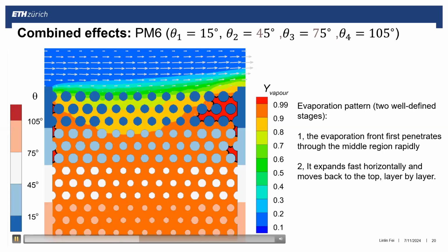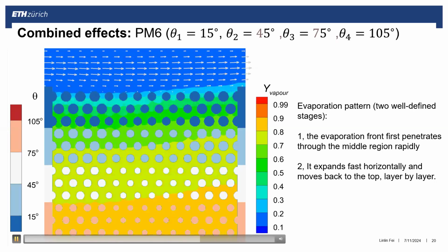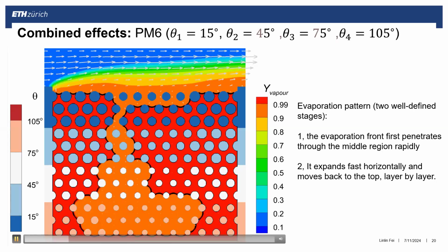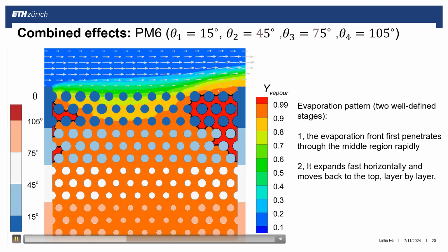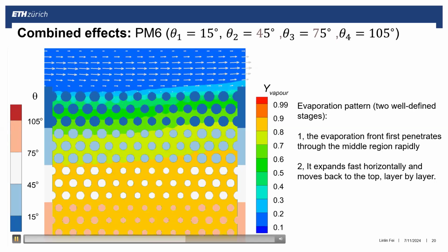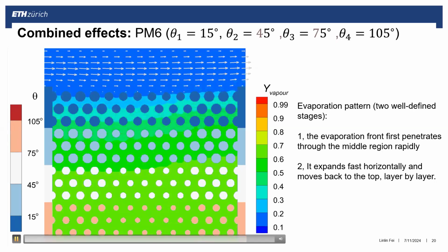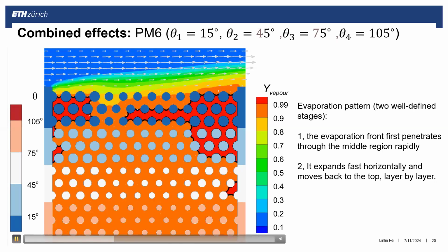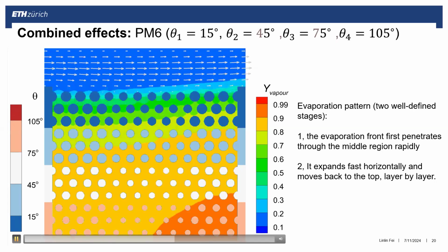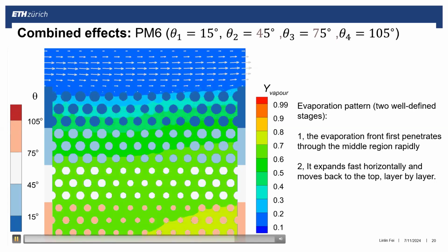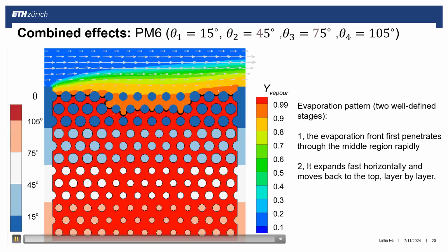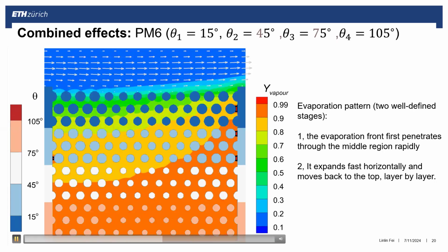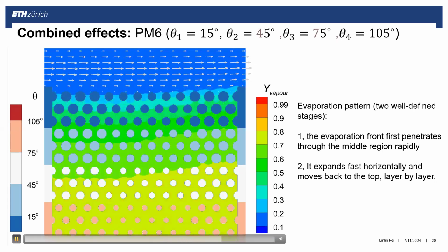Reynolds number is defined based on the inflow peak velocity and the gas viscosity and the channel length scale, not in porous medium. Inside porous medium, we usually don't talk about the Reynolds number. We care more about the capillary number. It's very small. It's in the order of 10 to the power -3 or 10 to the power -4.